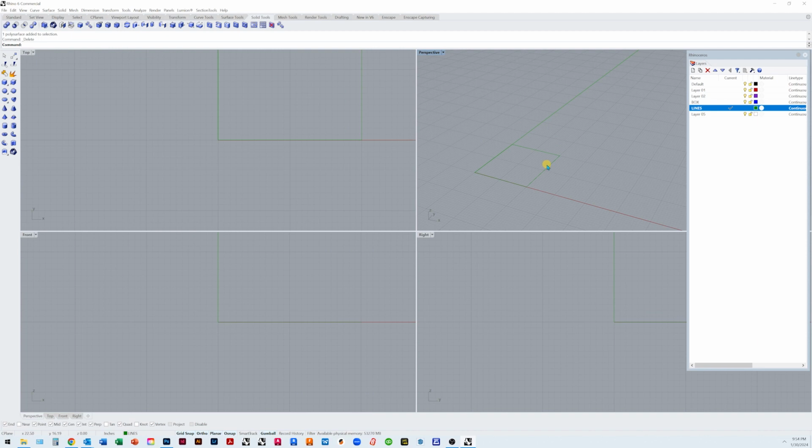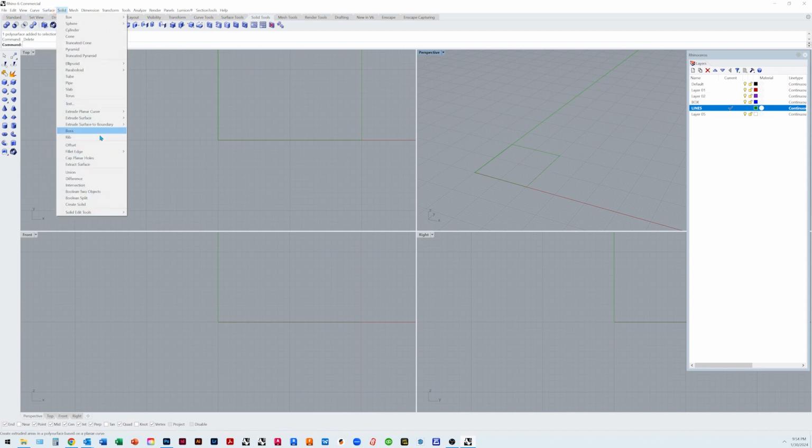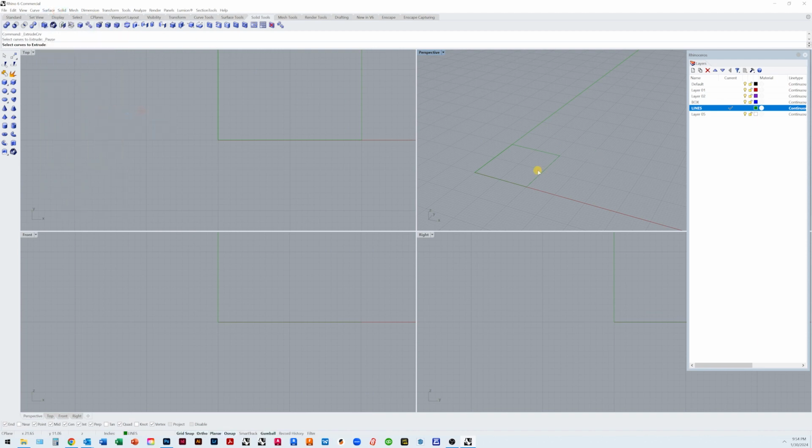So let's look at the other things we can do when we extrude a curve. Click here, click the line, hit enter. And it's going to ask me a couple things. It's going to ask me the distance we put in, the direction. Your mouse can show what direction it's going. Both sides, this one's kind of nice. This is a toggle. So if I click both sides, oops, it'll pull that extrusion from both directions.